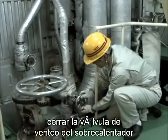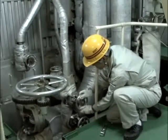Close the superheater outlet vent valve after confirming the steam flow.